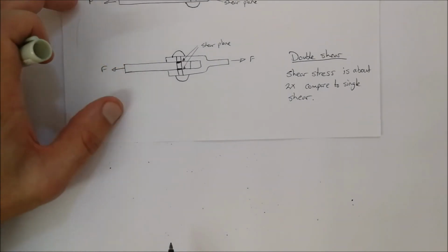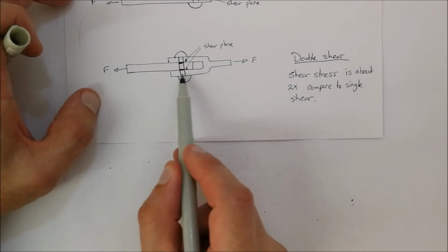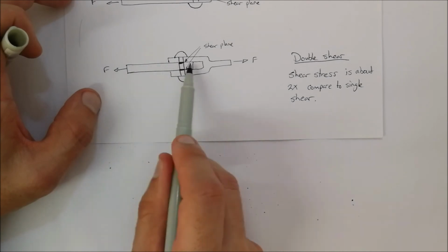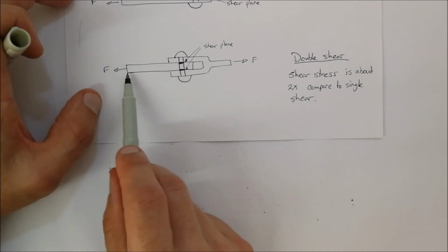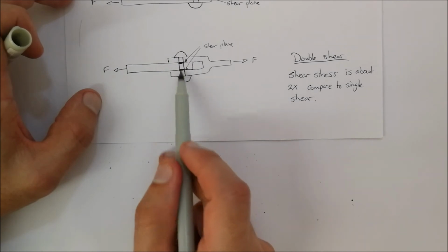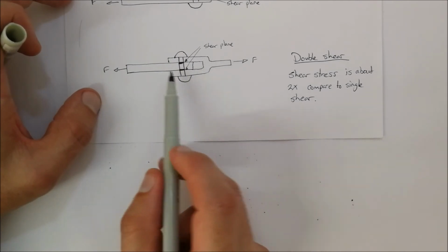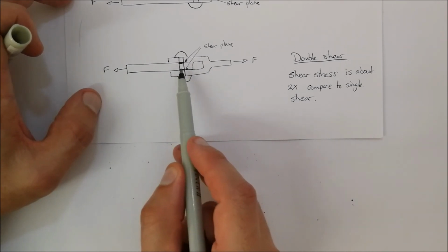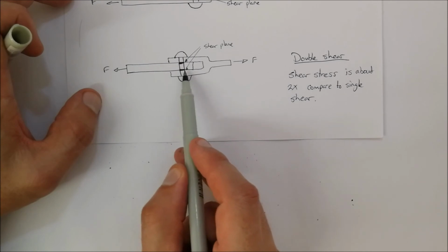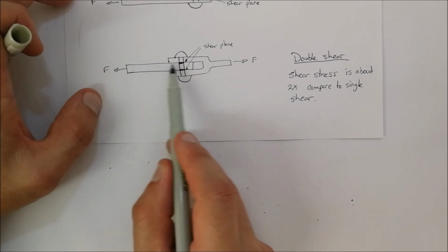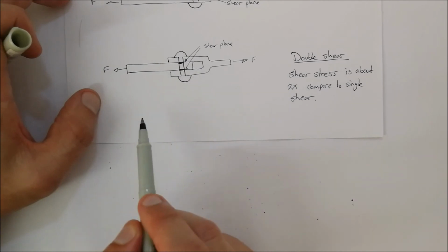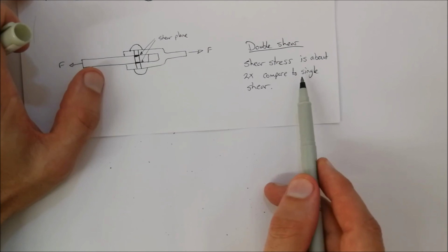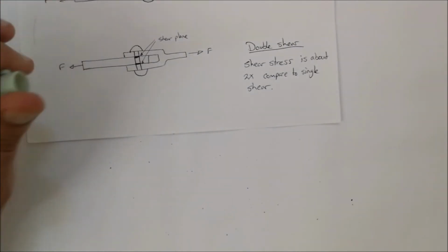Then we've got a double shear. So for example, you could have a fork-like structure over here where some force is applied to it, and inside that fork you've got a single piece of material that goes in there, and it's got a hole through it with a pin going through it as well. If you apply these forces and it's too much for either force, it will shear on both of those two points over there. So there are 2 points of contact where these materials are meeting, and therefore there will be a double shear happening. Okay, so keep in mind the double shear is about 2 times a single shear.